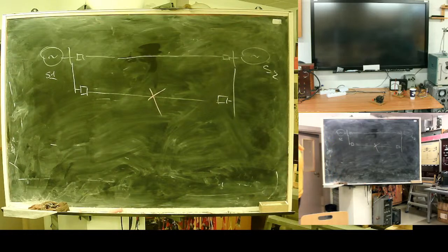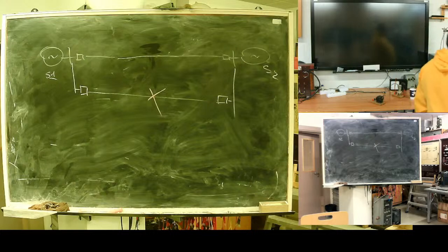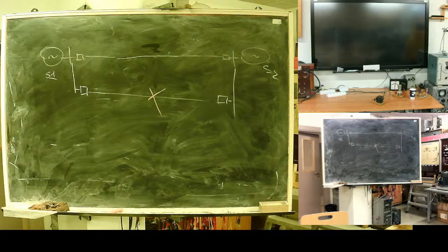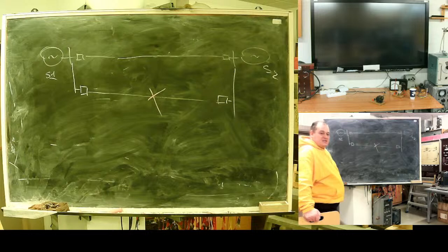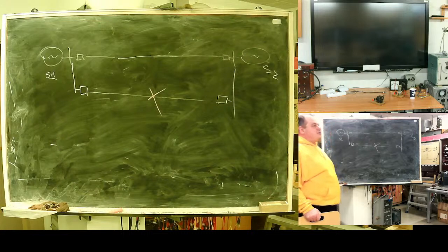Okay, two lines. The 1963 New York blackout: 5 lines from Niagara power. One disconnected, the others overloaded, the second disconnected, third, and we have loss of system stability and blackout. When we observe loss of stability, it's 100% possible that we will see a power swing.